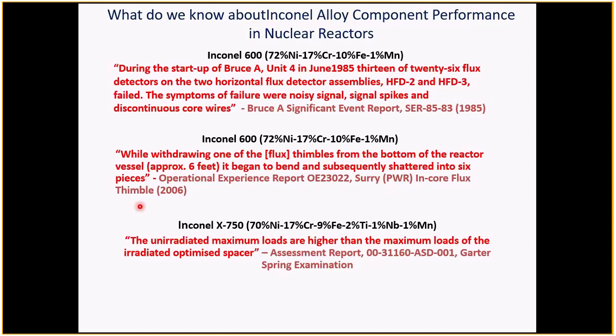Again, scary stuff. And then in our own CANDU reactors more recently, in the last 10 years, our Inconel spacers that keep the pressure tube separate from the calandria tube, if you remember the lecture on zirconium alloys, these things started failing. This is an OPEX now from about 15 years ago.